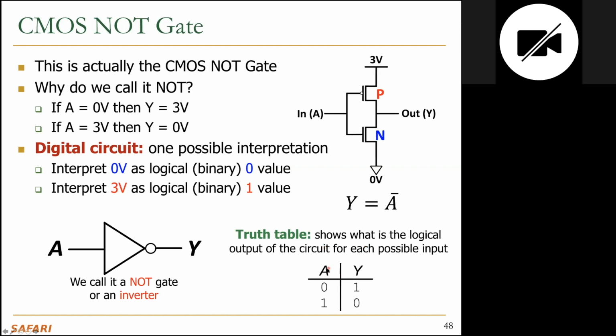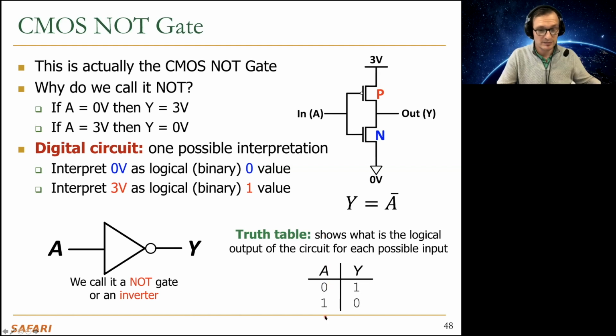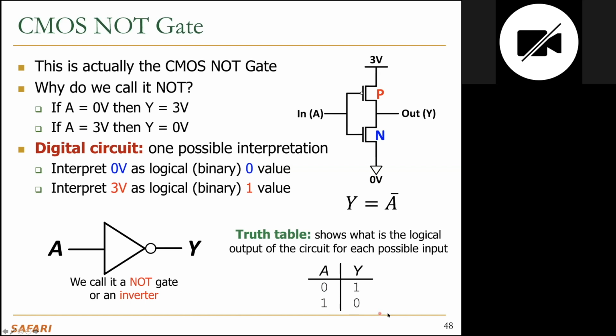You see this, right? So basically, on the left-hand side, one column is dedicated to input. There's only one input over here, a single bit input, A. It can take two values, 0 or 1. And the output, there's only one output, as you can see, Y. It can only have two possible values because input has two possible combinations, 0 or 1. And Y is essentially the inversion or complement of A. And this is the truth table.